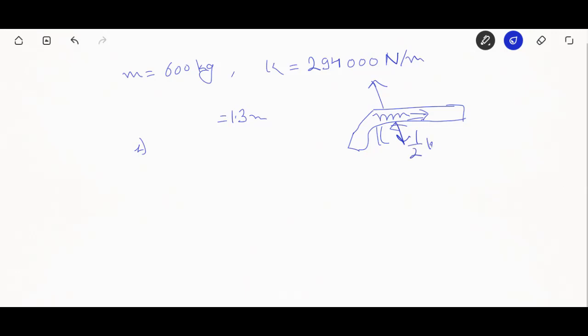So here we can see the energy stored in the spring. For the calculation of natural frequency, we have seen it is half kx square, right? Now this stored energy within the spring ultimately releases to the bullet and gives it the initial velocity v naught. With the help of this energy conservation method, half kx square is equal to half mass of bullet m v naught square, right? So by putting these values, we can get the value of v naught. My task here is not to make you understand the numerical calculation, but I am trying to combine those concepts that we have learned earlier.